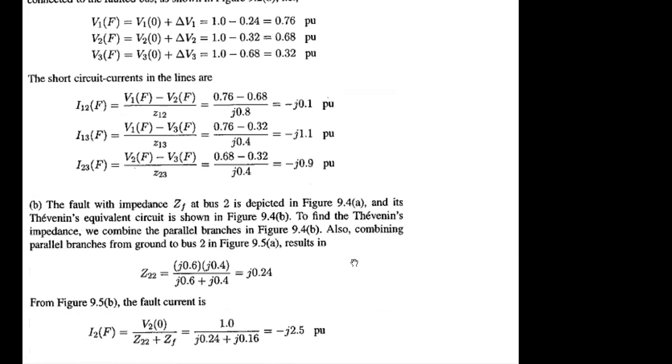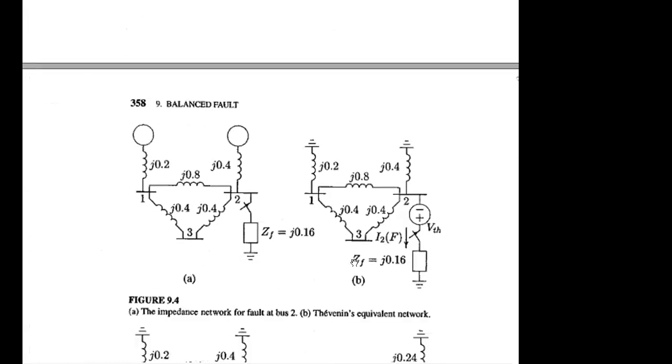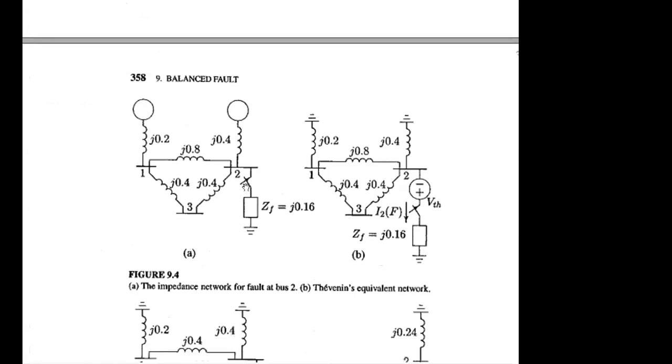I think that is now clear, so we can move forward to address the other bus. As mentioned, if the fault is at bus 2, what will be the fault bus voltage? It will be Z22, right? In that case the diagram orientation will be different. Now your short circuit path is attached to bus 2. Is it observable? Now we have the fault at bus 2. We have considered a second scenario for the 3-phase fault, at bus 2 instead of bus 3.